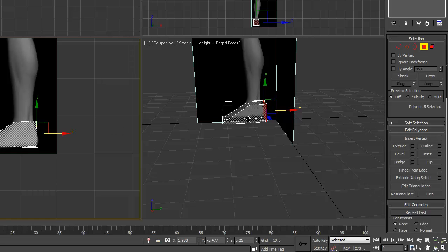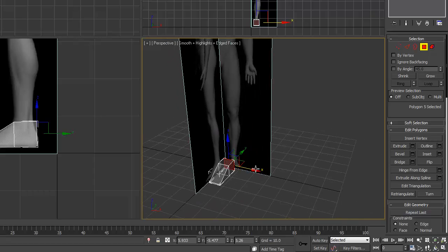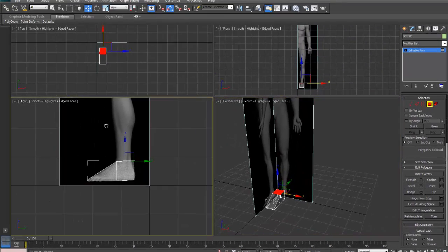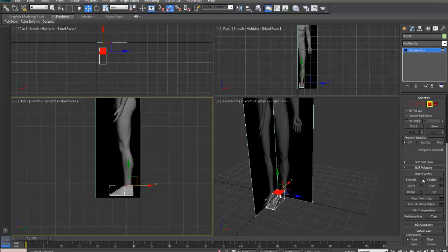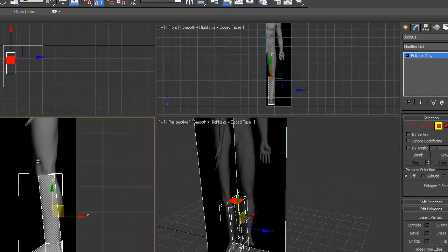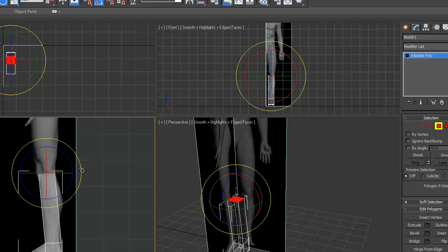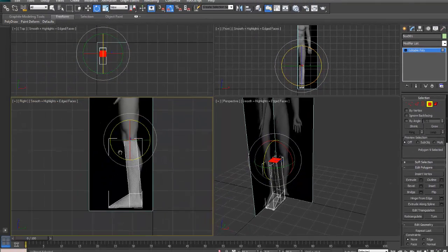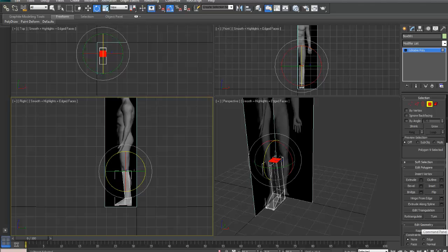So this is sort of the way this is modeled. We come to the top of the guy, and we drag this guy, extrude it again, just tick it off, grab that poly, and we're going to drag him up to this guy's knees, which is about there, halfway between. We also might just grab the rotation while we got it and rotate it a little bit onto the side like that, so it goes up on the same angle.